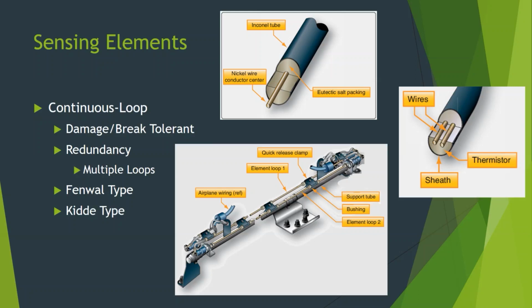If you switch it to A, you're telling the fire system on the airplane, only look at loop A, ignore B. What that means, though, is you've lost that kind of check and balance. So there's a higher likelihood of a false alarm when you're running on just a single loop. So why do we have the option to run on just a single loop? What's the reason behind that? Why not just say, well, if one of the loops is bad, we need to repair it right away?